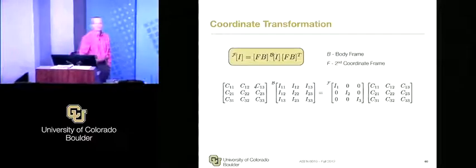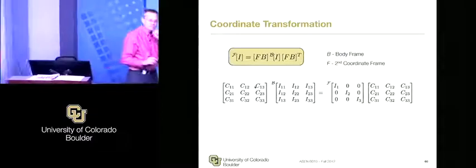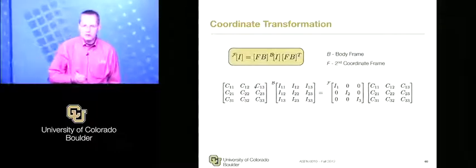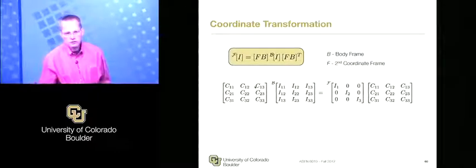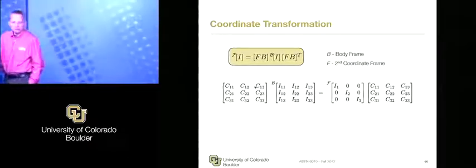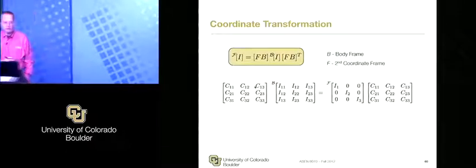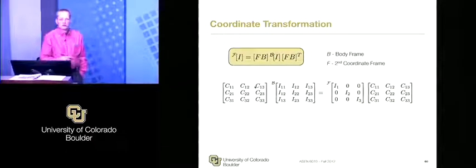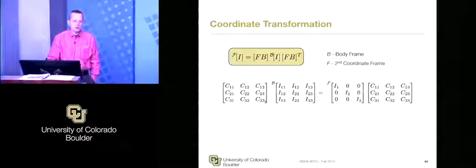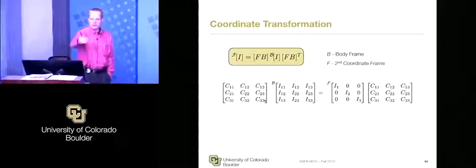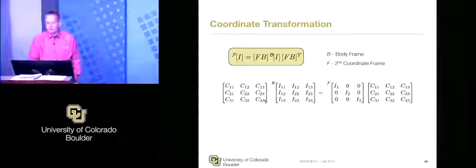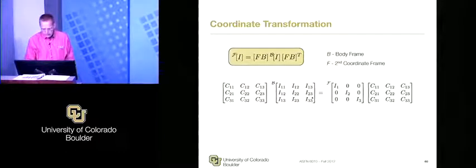What about this form? Your intuition is correct. It is positive definite. But what's one of the requirements for a matrix to be positive definite? All the eigenvalues are positive. All the eigenvalues have to be positive, right? And the eigenvalues for a rigid body will be positive. We haven't developed any imaginary weird structures that have negative eigenvalues all of a sudden. It's always going to be positive inertias, not negative inertias. Which makes sense physically. We're always adding up mass times distance squared for each little fundamental particle. Mass times distance squared, how can it ever be negative in a principal way? So anyway, yeah, symmetric, positive definite.